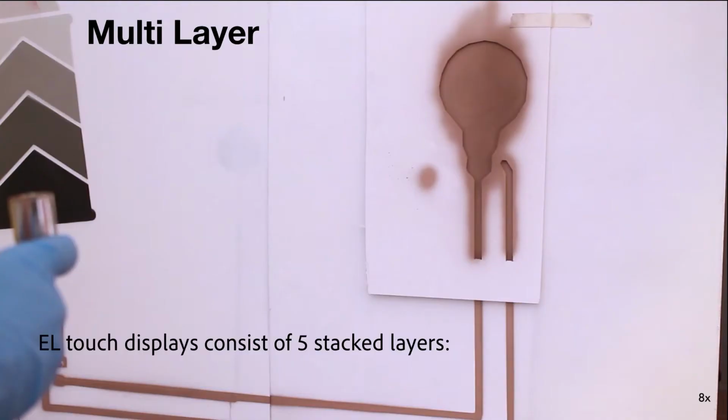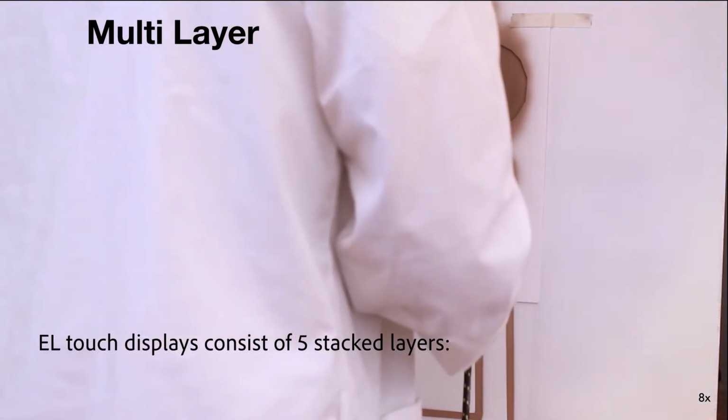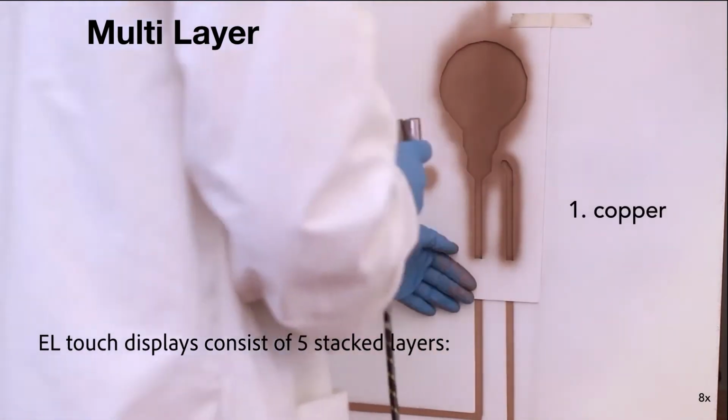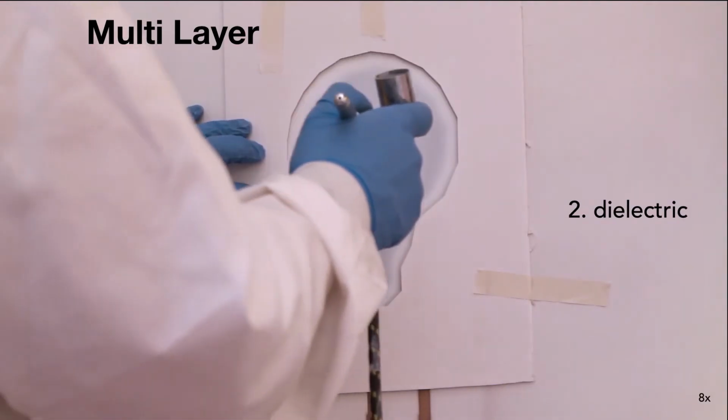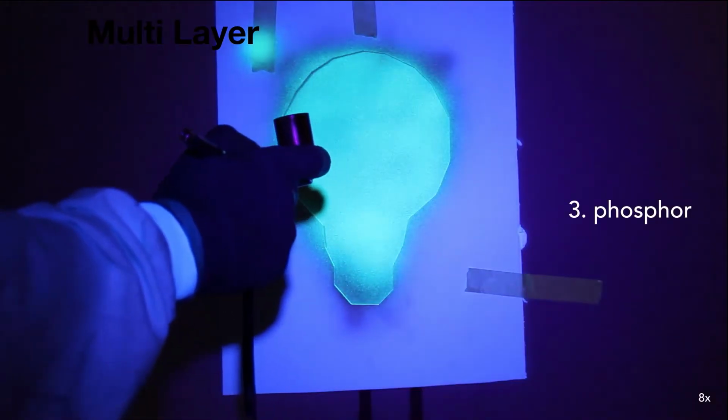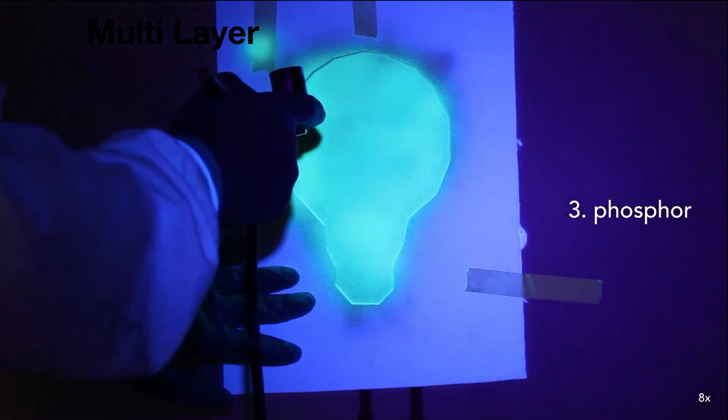Good, so how does the multi-layer fabrication look like, and how can we make electroluminescent touch displays with this approach? So here you can see how spraying a display looks like. We first start with one layer of conductive copper that you spray in a specific shape, here supported with some fabricated stencils. Then you add a dielectric layer, a light-emitting phosphor layer.